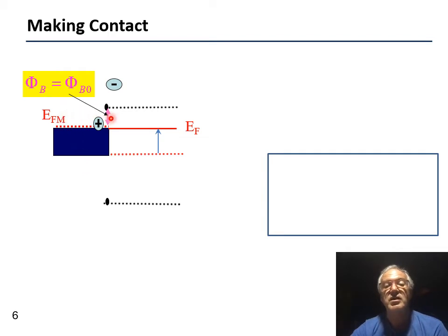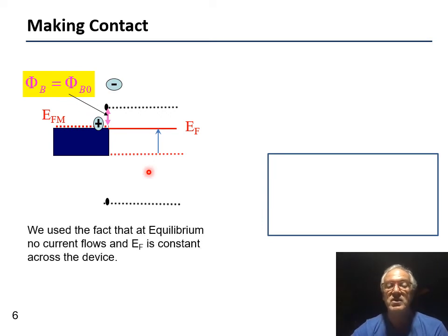And you've noticed here that there is this mismatch between the Fermi level and the conduction band, and in this case we'll call this an energy barrier, which is marked here by phi b. So basically what we did here, we assumed that we are interested in the energy levels under equilibrium conditions, and in that case we waited long enough until everything stabilized and there are no currents in the system, and the Fermi level is constant. So this tells us what's happening close to the interface.